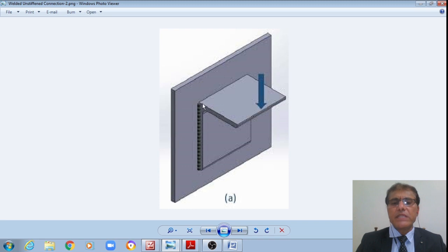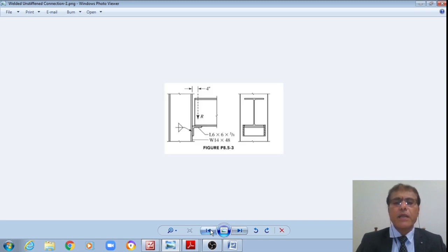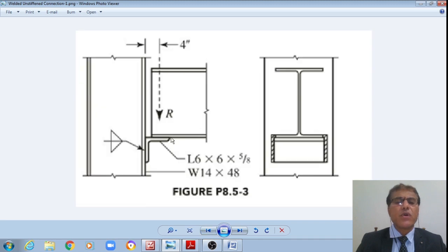And just now we have designed this weld size as root 2 multiplied by 5.46, or say 8 mm. And also I have to have a beam provided here. Let me show this. This is 200 mm, this is 150 mm, student.